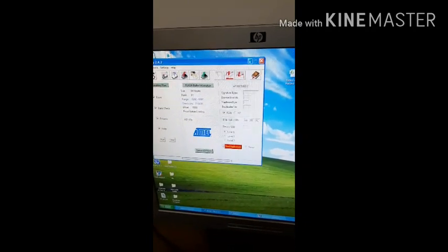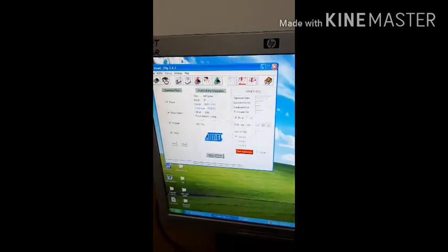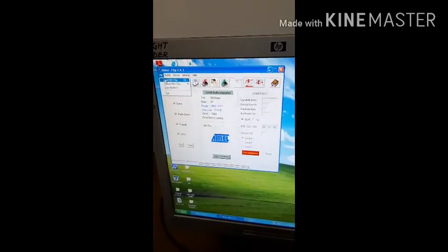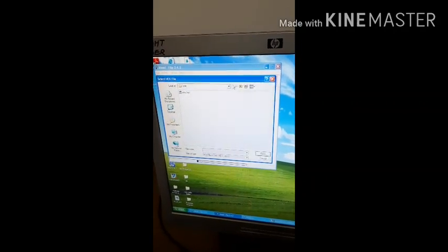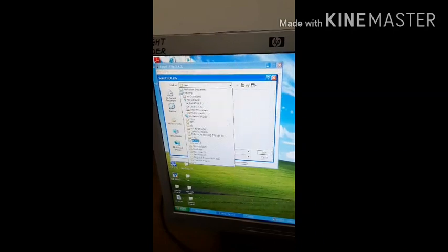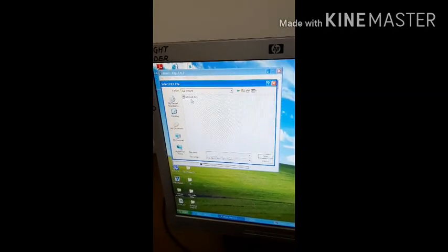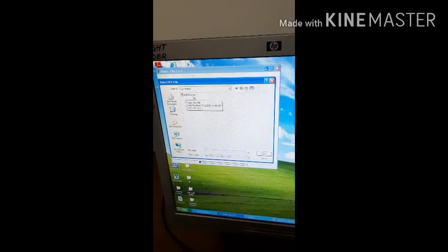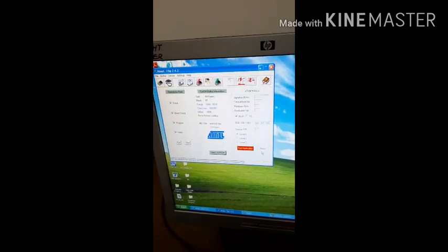I will connect it. So you can see here the start application. Once the start application comes, you know that you will have to get the hex file. Now I will go to this folder where I have stored my stepper motor program, and anti-clockwise.hex. This is the hex file which is created, that will be opened now.